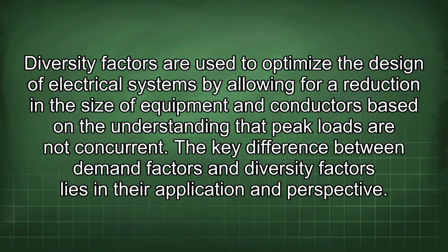Diversity factors are used to optimize the design of electrical systems by allowing for a reduction in the size of equipment and conductors based on the understanding that peak loads are not concurrent.